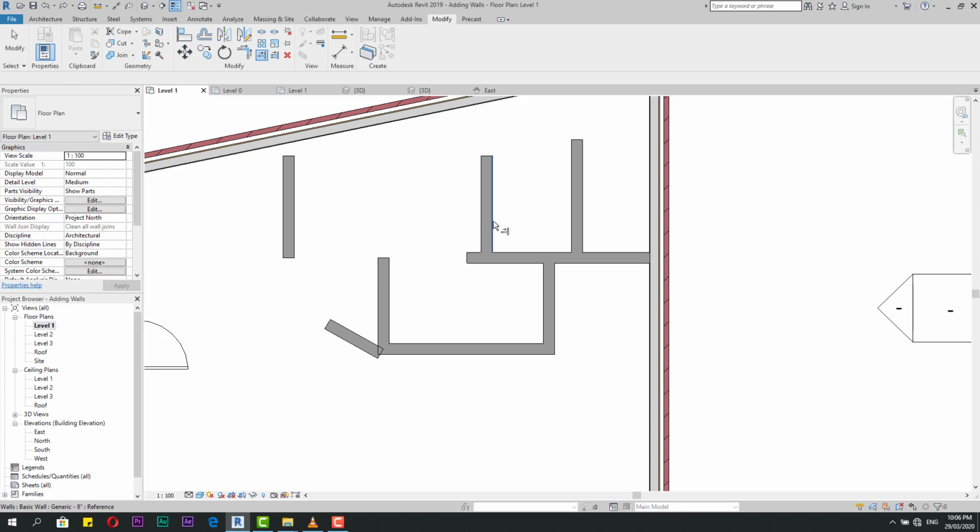The same thing if I select this and click here, take care what happens. It will cut at this point. There is a point here and a point here. If I click here, it will cut the other points. Okay, it works like a knife, a sharp knife, it cuts what you need. Okay, this is the meaning of extend and trim.